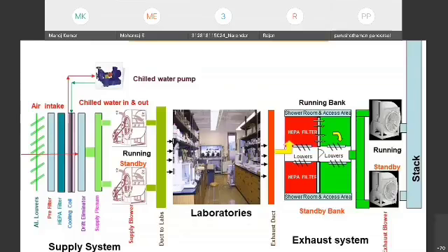And generally, in the recirculation system, after all this, the air is sent again to the front. But we do not follow this in a radioactive system, because once it gets contaminated, it should not affect the other rooms. Though this is a costly affair, because each time we take air at around 35-40 degrees and cool it to 15 degrees, whereas in a recirculation system, the air here becomes around 20-25 degrees, and again at 25-26 degrees we would get the air here.